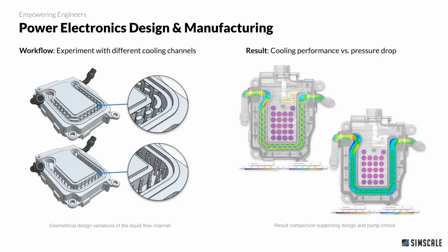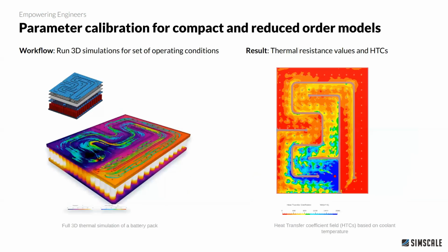You can also use SimScale to do extensive design iteration. So in this case, on the inverter model, just changing the liquid cooling channel a bit. You can upload as many variants as you want, replace it in your simulation setup, and just hit start again. The assignments can be mapped. So that is basically no manual effort that you need to do here, but you get a lot of insights and can make informed decisions early in the design process.